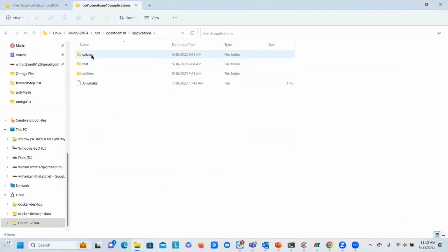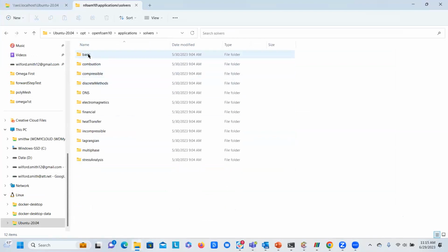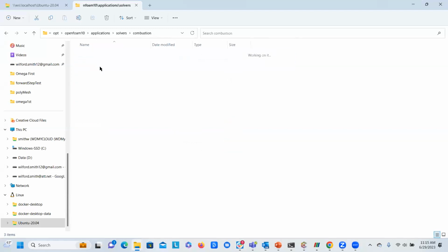These are all the application areas that OpenFOAM has. For example, there's basic, which is just introductory. It has some potential solvers, some Laplacian solvers, and some scalar transport calculators. There are combustion calculators in there. One is just a straight-up chemistry calculator, and reactingFoam, which is essentially a reacting flow, including all the Navier-Stokes terms, for incompressible reacting flow.